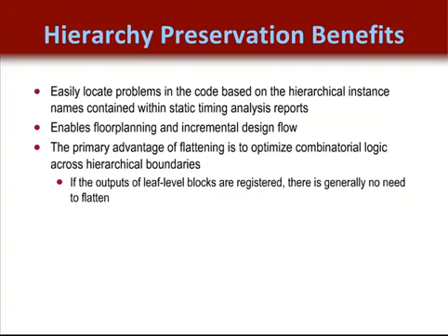Note that most experienced designers know that for optimum speed they need to make sure their timing critical hierarchical boundaries have registered outputs. This is a pretty standard way for users to tolerate a high fanout net that a component might be making, or if they know the placement of the destination logic might be far away. But commonly, when a designer makes a purely combinatorial piece of logic, adding a register can easily be accomplished by converting the component to a registered component. If the component already has its outputs registered, then optimizing across a hierarchical boundary will have no effect, since logic optimization will not remove the register.